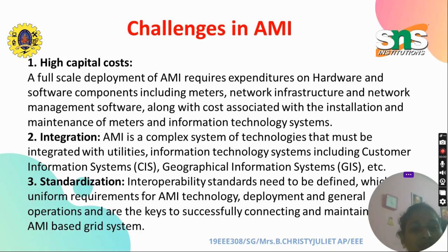But what are the actual challenges in installing this AMI? To create this AMI infrastructure, we need to face a lot of challenges. The first is high capital cost. A full-scale deployment of AMI requires expenditure on hardware and software components, including meters, network infrastructure, and network management software, along with the cost associated with installation and maintenance of meters. We also need to track information, so we need to incorporate a lot of digital equipment along with this hardware and software, so it requires a high initial cost.